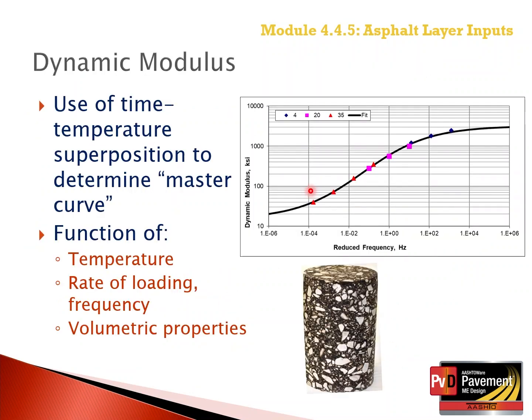The PMED software uses the concept of the time-temperature superposition principle to create or generate a master curve for the asphalt layers. This chart illustrates a typical dynamic modulus master curve that is generated by the software from the dynamic modulus test results measured in accordance with AASHTO T 378.